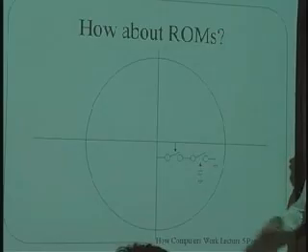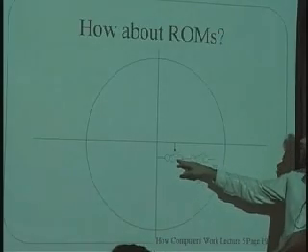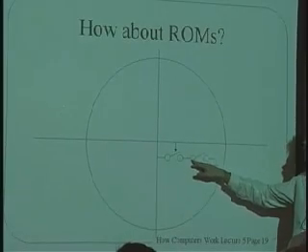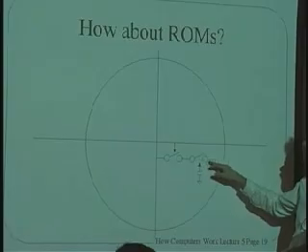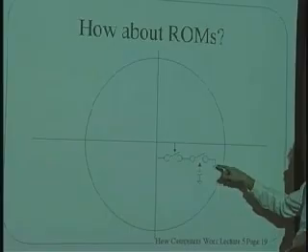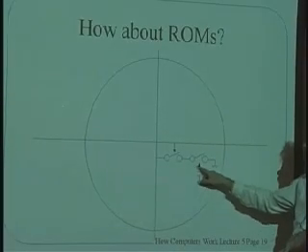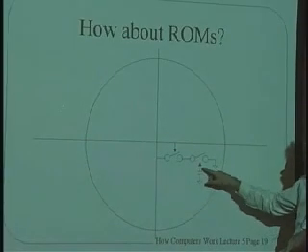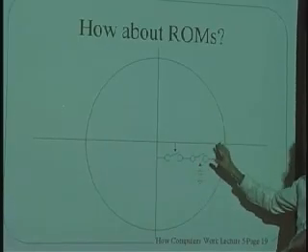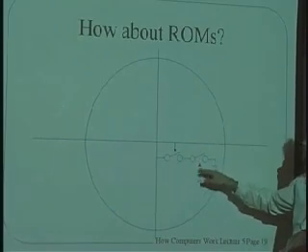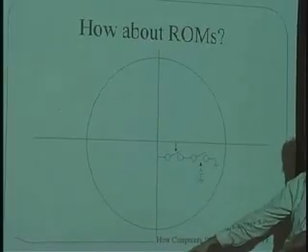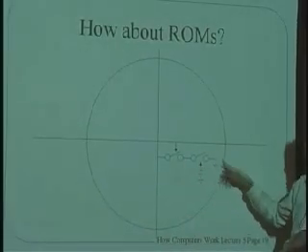Structure's a little bit different. The row selects a switch, and that chooses this path here. And this path is not a capacitor, but is in fact another switch, which goes to ground. Ground is the symbol here. Basically, if this capacitor here, which is floating out in space, has charge on it, has energy in it, this switch will be closed forever. And if this switch closes and this switch is closed, then this wire will be connected to ground. And there's a sense circuit down at the bottom that tries to put a little bit of current in and see whether or not it's hooked to ground.